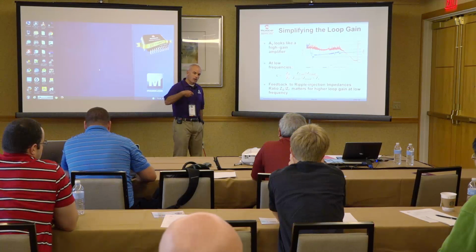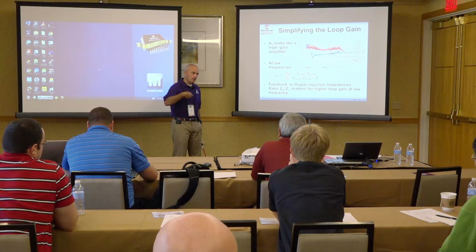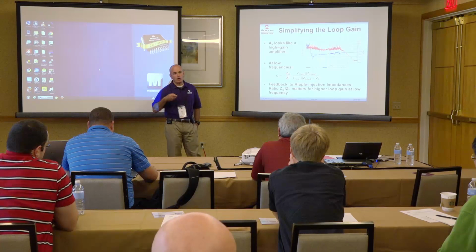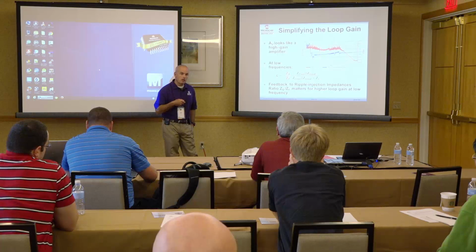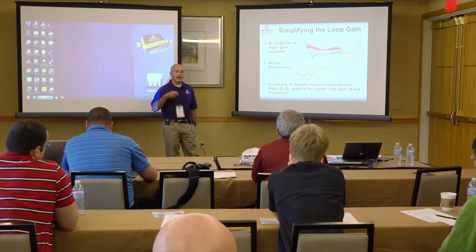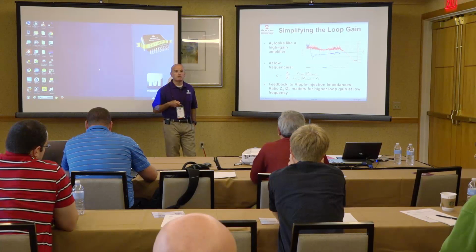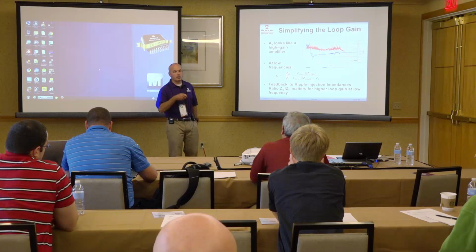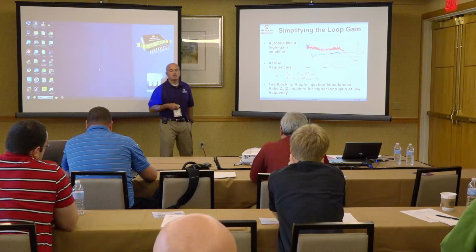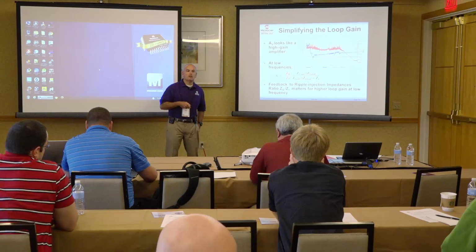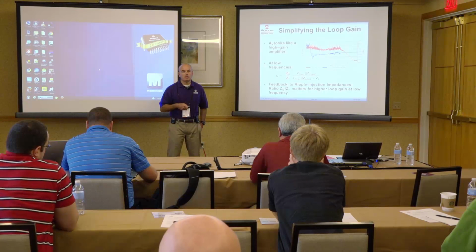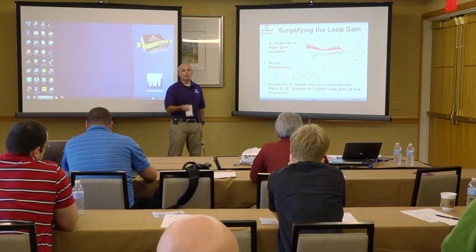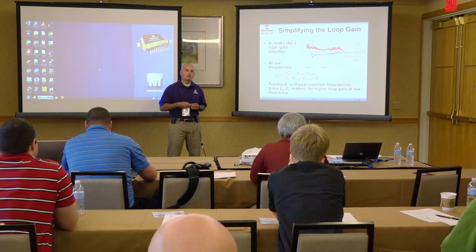Well, if you are not injecting ripple, you'll end up in stability problems. I assume that you obey the rule of 4 times the ESR ripple, then you don't need to put the network. That's your best case as far as